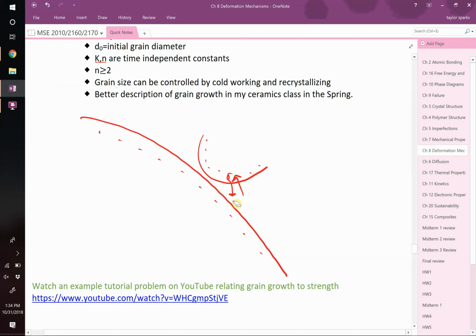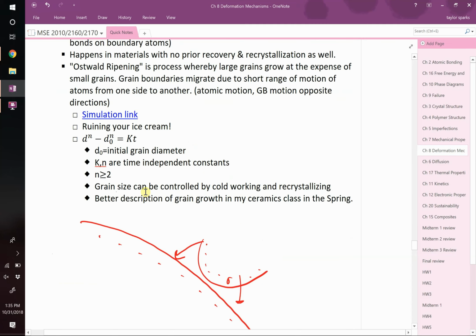So it literally can be calculated, the mechanism of this, assuming solubility. Literally the solubility of these guys, because of the strain, which is exactly what you mentioned, is higher, and these have a lower solubility, you're going to see a net migration to the surfaces of the large grains. Okay? Which is pretty rad. It's not pretty rad when it ruins your ice cream, which it does.